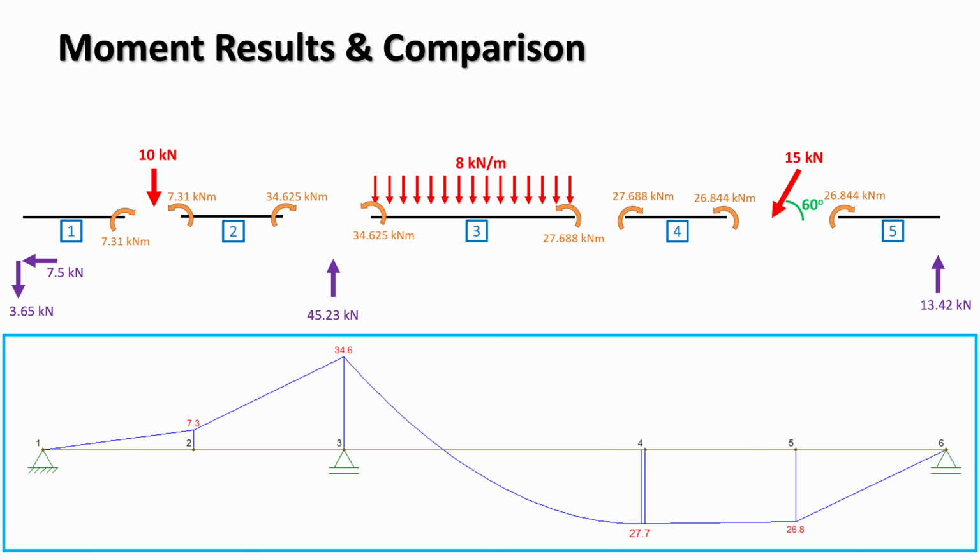At the bottom, the bending moment diagram from F-tool is shown, and the results match exactly in magnitude, sign, and overall shape. This confirms that the bending behavior has been captured correctly, including the rotational degrees of freedom and the contribution from the distributed load.